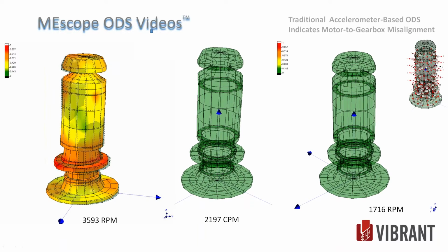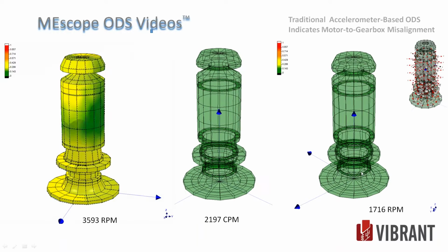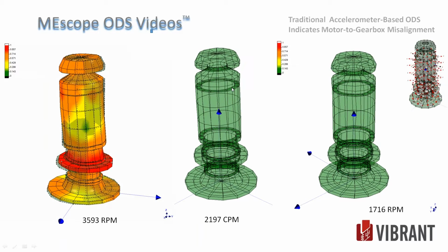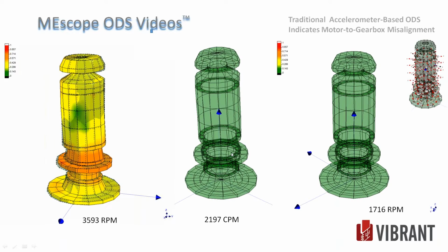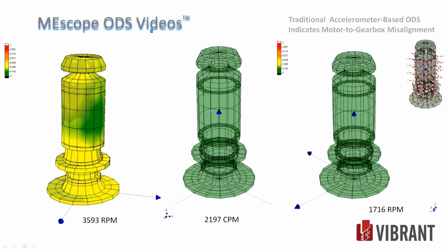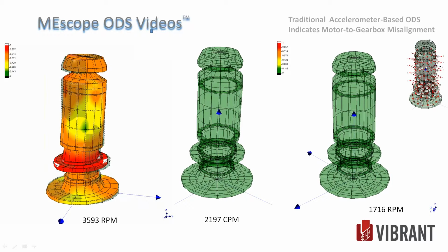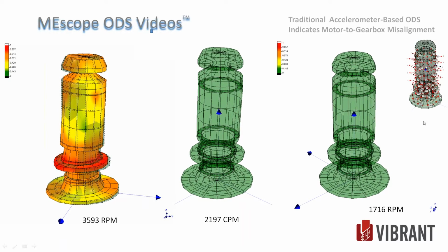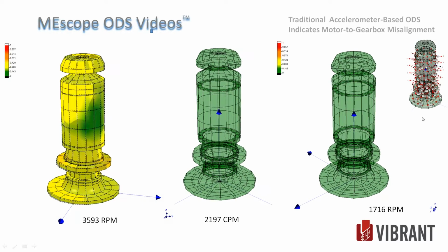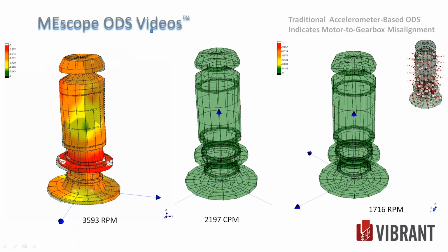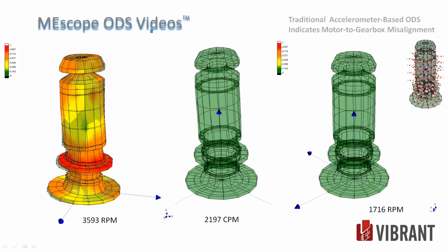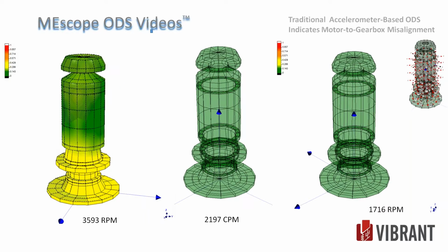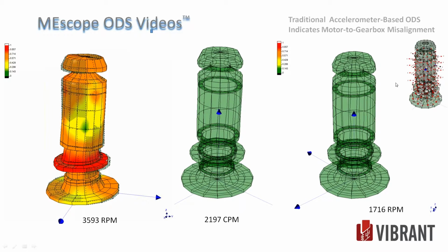So I don't know if I missed this mode. It was very low amplitude. This was one of the bigger rigid body modes in there. I did take a lot of data. If you look over here, there's rings of 8 measurements, and each measurement's a triaxial. There was probably 80 times 3, 240 or so measurements collected on this for the ODS analysis.